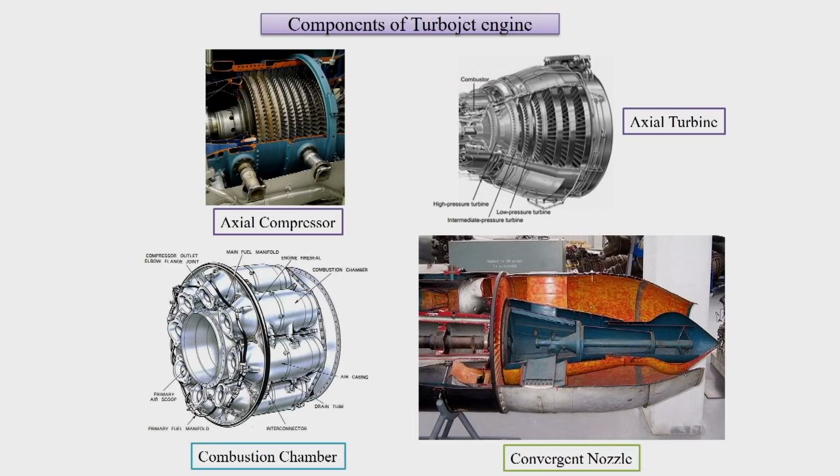So the intake would also compress the air, and that compressed air would go to the compressor, and then we would have the combustion chamber where fuel is injected for combustion with high pressure high temperature air. Upon combustion, pressure is expected to remain constant, but temperature would increase, and then our nozzle is expected to increase the kinetic energy.